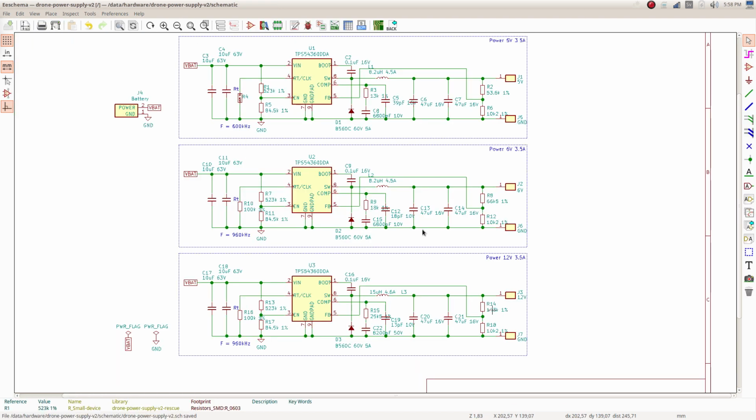So I'm not going to go through all of the components, but you kind of get the idea. And for example, the battery component, there is usually in KiCad you have generic symbols. So generic symbols go that far, but they don't go all the way. So it's kind of like in Altium Designer you have your vault, and you can download components from the vault. But I find it a better approach to download the components that are already done, so you don't have to redo them, but then to have a local copy of the components where you actually assign more details to the component that are unique to you.